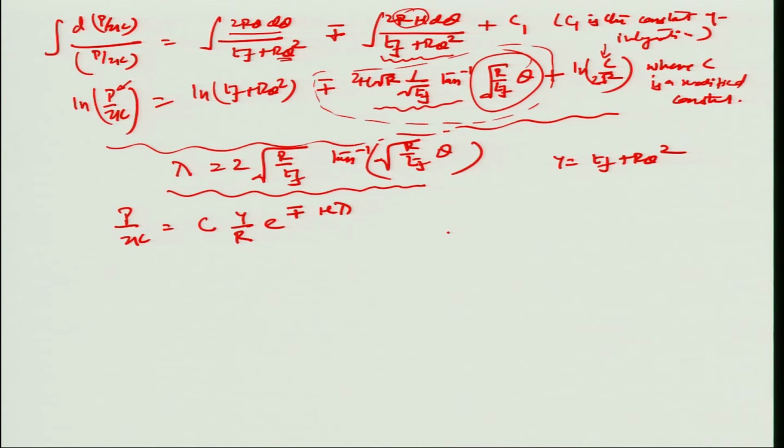this would necessitate, so we already know that our initial pressure Pi of the roll plus the sigma xi, which is the initial reaction force in the inlet side of the roll, should be equal to twice k by the von Mises criterion.